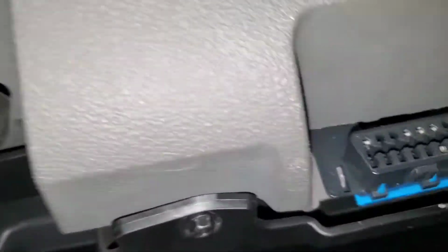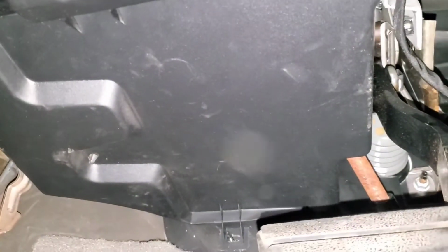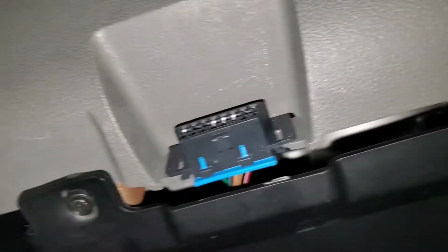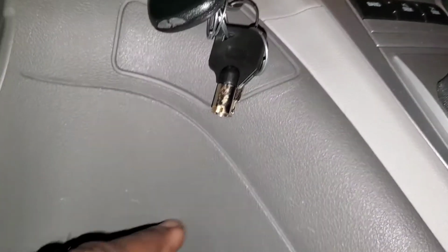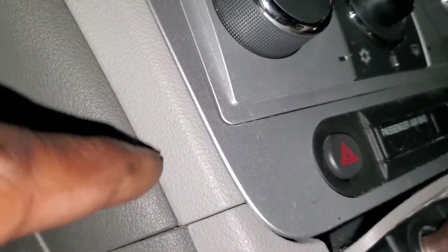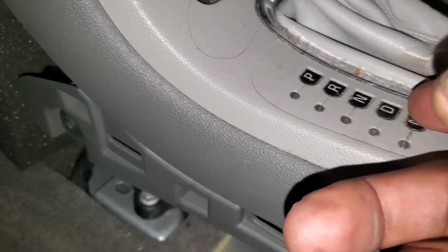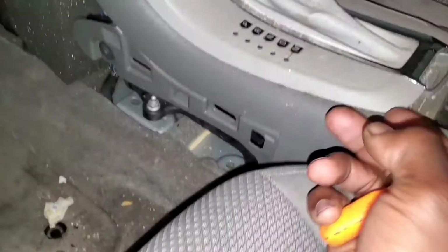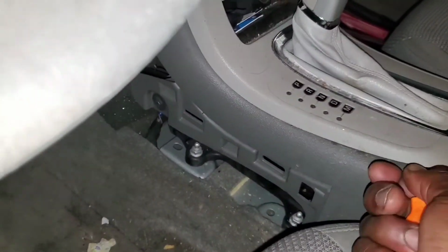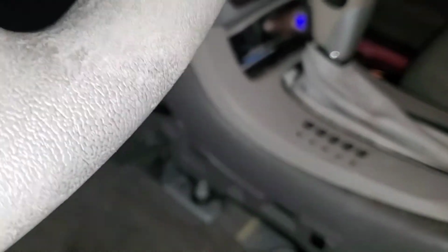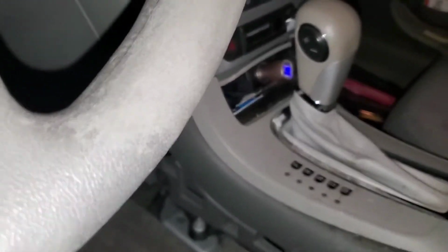There are a couple. Actually, that's not the panel that comes off next. The under panel here comes off next, and it's retained by two screws there and clips. Those screws also retain this, but this panel has a hidden screw somewhere in here. I don't know where it is yet, but to get to it, this trim piece has to come up. So you pry it up back here, easy enough, comes up, and it slides back.